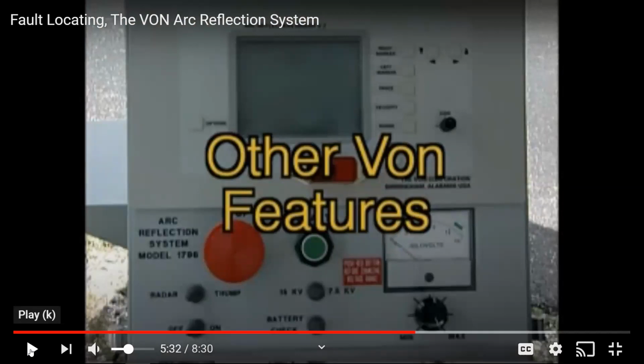Okay, so it goes on to other features of the Von Thumper, which are pretty in-depth. You really don't need those right now. What we did on our machine is most of our faults were on a certain size cable, so we just set it that way and left it that way. The rest of the video just goes into more technical features. All right, so once you've located it like that with the Von Thumper, dig it up, splice it, and you're good to go.